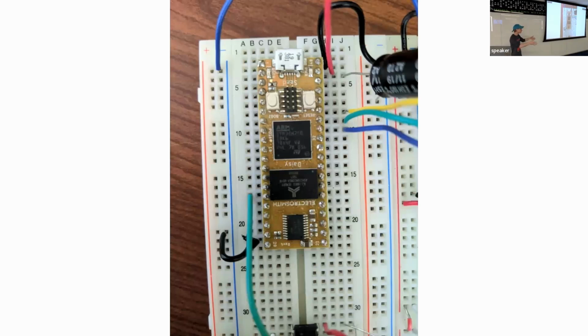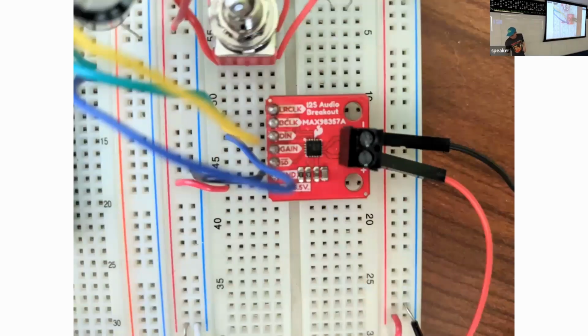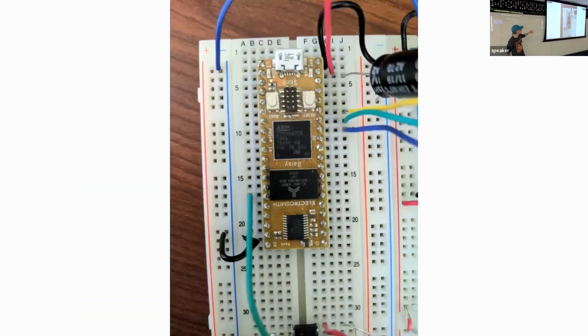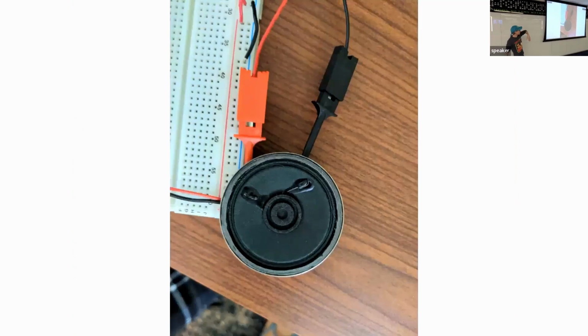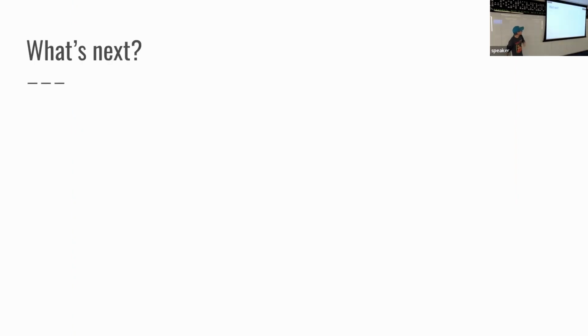puts these voices into place, and then the audio interface here on the microcontroller just continuously, when it needs audio, calls our program to get more, and then it sends those over to this audio codec down here. So I guess in this case it wasn't wired up to do that. The audio is coming out here on these 3 wires, and going into the SparkFun device, and then coming out as analog audio and getting playback.